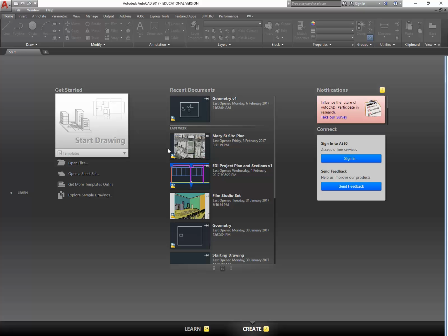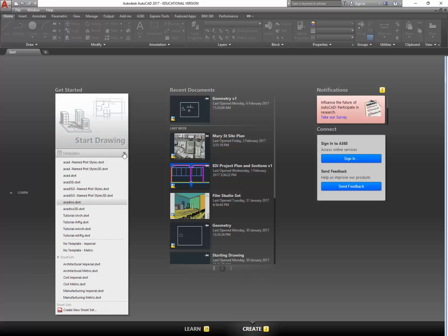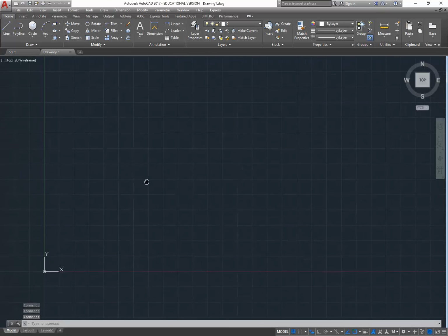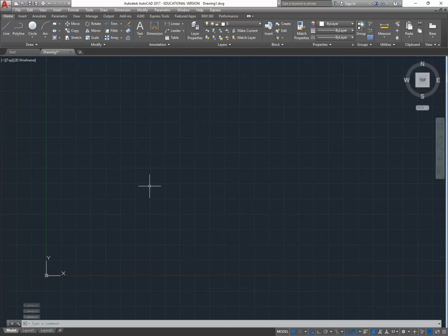So beginning with AutoCAD, that I've already got open, I'm going to start a new file, and a good habit if you're not already doing this is to check the template that it's using and use AutoCAD ISO if it is metric. If you're the only one using your computer, that won't change, but if other people are using it, they might have changed the template. So AutoCAD ISO, not AutoCAD, AutoCAD ISO without anything else. So that's metric. That means you've got AutoCAD architecture open.